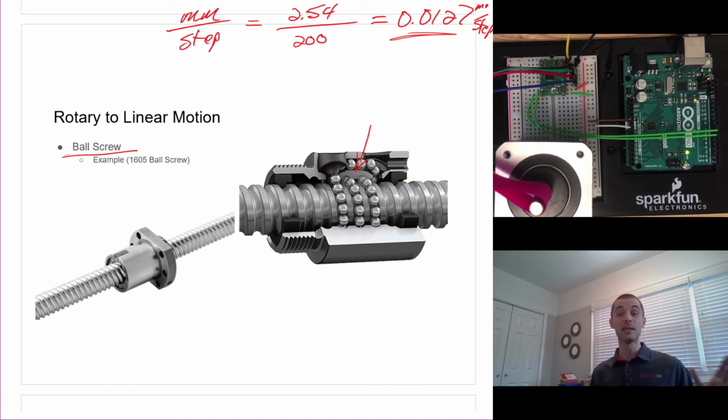You can buy very inexpensive ball screws, which are still probably more expensive than the belt systems. Or you can buy very expensive ball screws, which go in a lot of those industrial machines, like some of the CNC lathe and milling equipment that we have in SG01. They use expensive ones, right? But that's because they're trying to obtain very accurate movements so that you can make very accurate parts, or essentially very precise machining of components and features on the parts that you're creating.